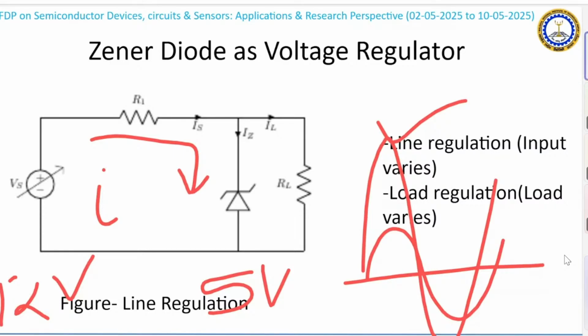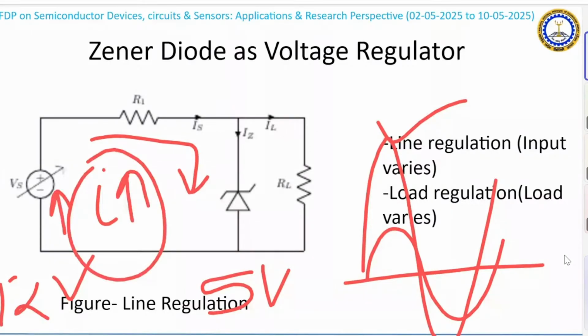In that, if I have a particular rating, because I have presumed that all the input signals will be within the rated volts, then in that case my device is not able to handle the increased current. And if this is so, what is going to happen? There is the possibility that my device is getting damaged because of the I square RT heat dissipation. That's the heat dissipation.